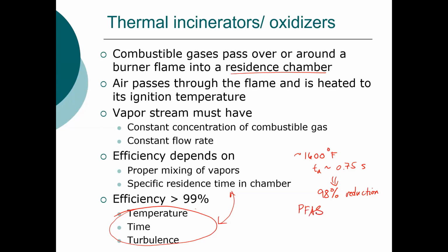On the other hand, if you wanted to look at PFAS incineration, you're looking at temperatures of about 1,000 degrees C, so over 2,000 degrees Fahrenheit. So you're looking at much higher temperatures in order to oxidize and incinerate PFAS-containing materials. In Michigan, we do not have an incinerator that can actually treat a waste stream at that high temperature.